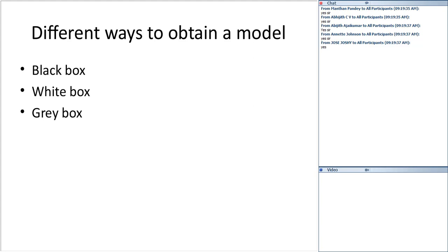So finally gray box, which is a hybrid approach of both black box and white box. Say you know what is there inside, but you don't know its parameter values. Say suppose you have an RL network. By applying KVL you know the differential equation, V is equal to IR plus L di by dt. But you will be finding out the values of L and R from the experimental data by applying some known inputs and by measuring outputs. So gray box is a hybrid approach. It is a combination of both black box and white box modeling techniques.